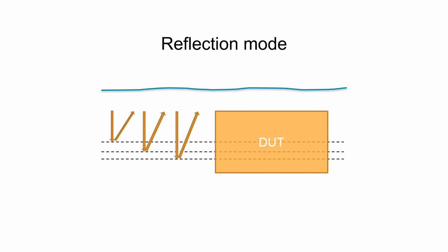We mentioned that acoustic microscopy is a time-of-flight type of measurement. Time-of-flight uses timing gates, which can be set to capture reflections from specific interfaces located at different depths in the device. The transducers have different frequencies. Low-frequency transducers can penetrate deeper or through the device. Higher frequencies have a shorter penetration depth, but give a better resolution.